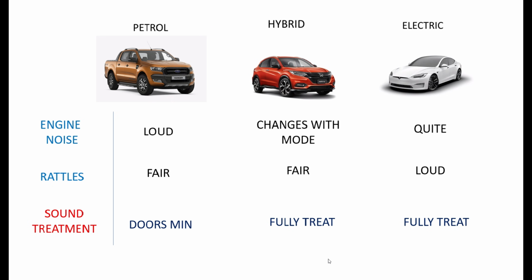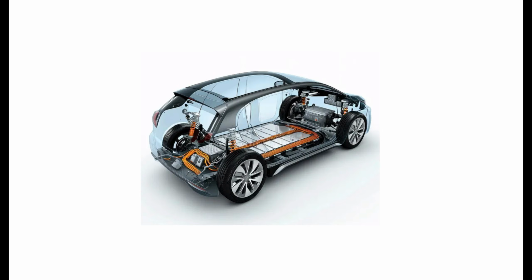So if you've got an electric vehicle, it's not recommended to sound treat the floor, because you've got heat dissipation issues and things like that. Adding sound treatment will effectively add a layer of thermal barrier there, and you don't want to do that. You don't want to interfere with the car's ventilation of the battery system at all. So be careful of that. All right, so that's really sound.